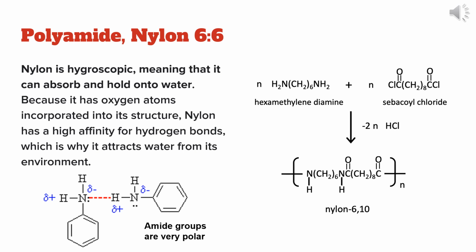Plasticization occurs when the water molecules bond to the chains of nylon molecules. This means they're more likely to slide over each other at a molecular level. When plasticization occurs in this way, the strength of nylon parts decreases.